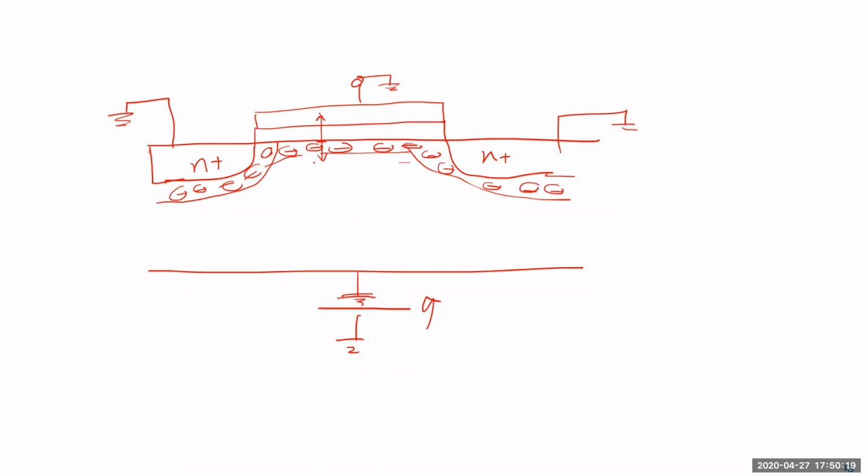The argument is that I want the VG to be such that it tells me how much extra voltage I need for the surface potential because of the depletion from the gate voltage, not from the diode. But the band diagram is a little bit complicated because now you have a lateral and a vertical structure, so it becomes tricky.